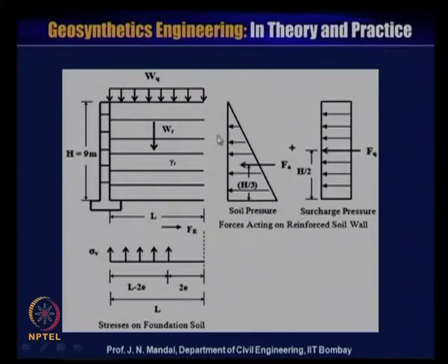But in this example we are only considering the soil pressure and the surcharge pressure. So you have to check what pressure is acting, what forces are acting on the retaining soil wall. The reinforced soil wall rests on the foundation soil, here the foundation soil.